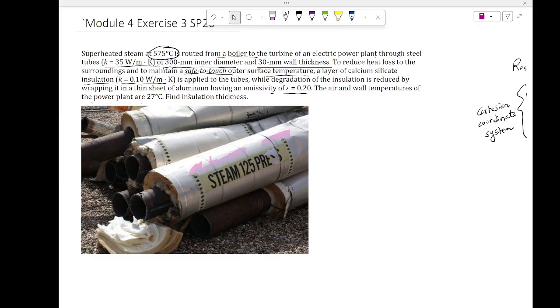All right, now this steel pipe is carrying steam at 575 degrees Celsius. If you somehow touch it, what is going to happen? It will burn immediately, and it's a serious burn. You're not touching boiling water. 575. So what is the safe touch temperature? What could be safe to touch? It must be less than 100 degrees Celsius for sure, right? Must be less than boiling temperature. Now, usually 50 degrees Celsius is the safe touch temperature.